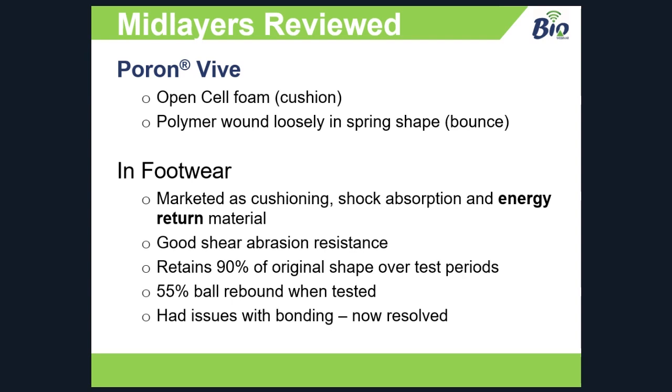It's got pretty good shear abrasion resistance. If you've got any product samples or offcuts, just get this material by itself and try and tear it. Without any fractures or cuts in the material beforehand, if it's still quite good quality, it's really difficult to tear. So that indicates that it's got good shear resistance. Hard wearing, we'll say it retains its shape, so it means it'll keep bouncing a lot, and it doesn't tend to dissipate over time.